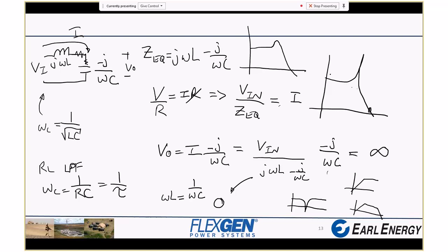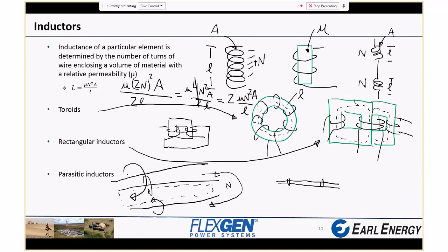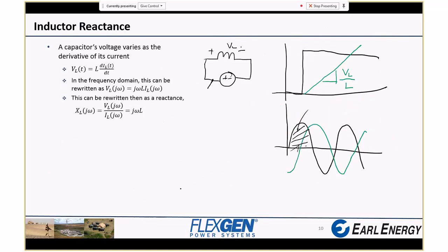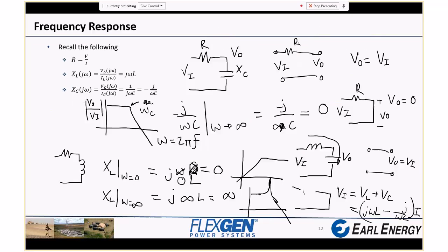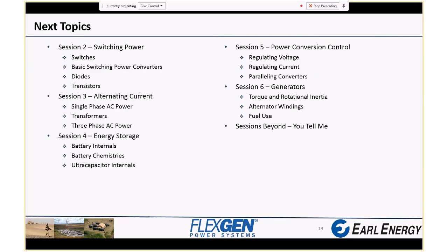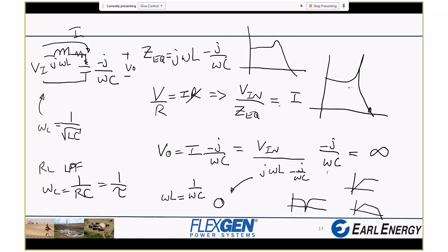Phase shifts due to the L's and C's, like this phase shift of voltage versus current, and the similar phase shift we get in capacitors of voltage versus current, can cause instability where the control loop sees the positive side of a sine wave and decides, oh good, I should give it some more positive sine wave.